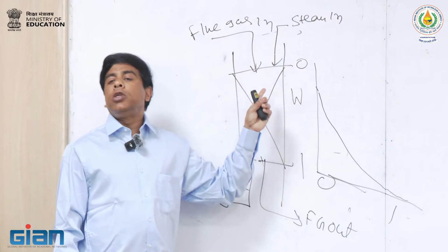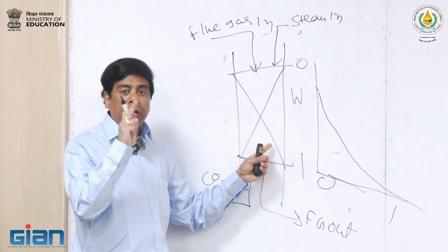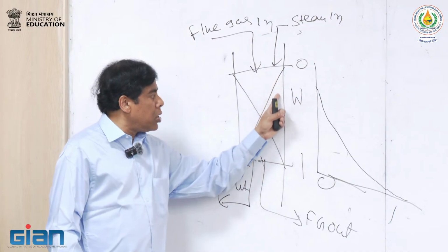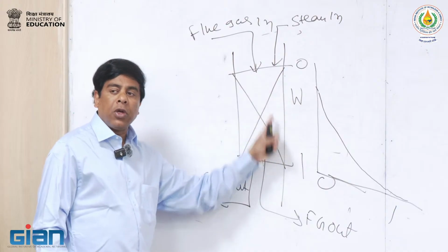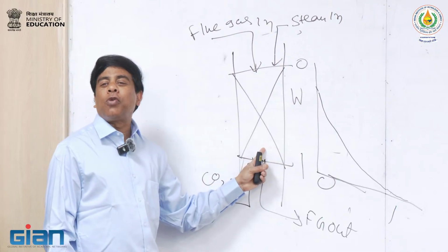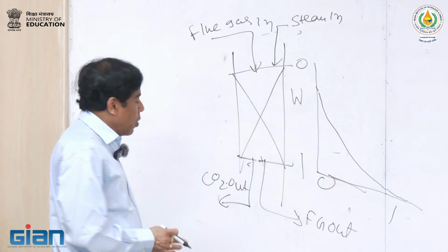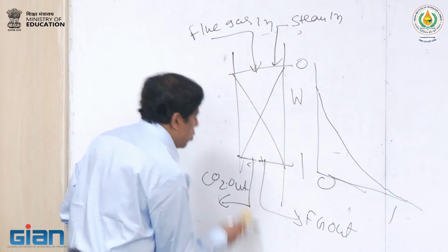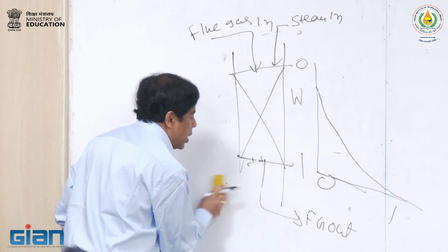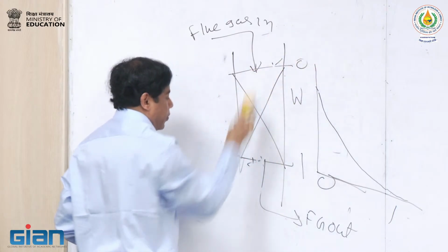So basically, we are desorbing from one section and adsorbing in another section. That mathematically makes sense, and in real life these observations are also made. The problem is that you are not really desorbing the bed, because the CO2 is readsorbing here. To complete your desorption cycle, you have to keep passing the steam that you desorb from here, then desorb from here, and then finally desorb from here.